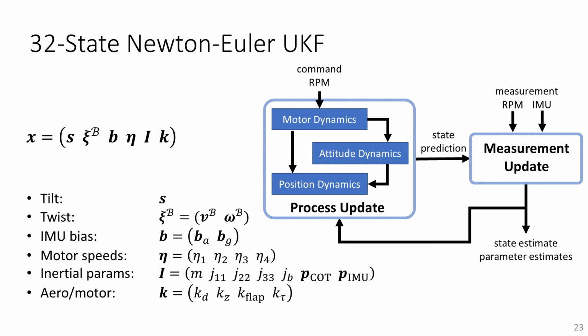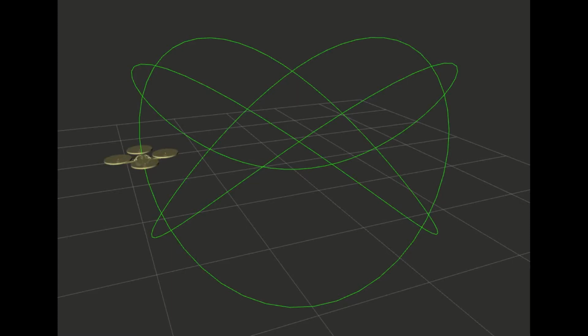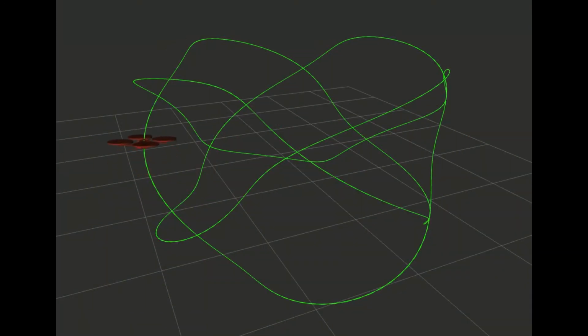Intuitively, this makes sense. Some angular excitation is necessary to estimate the rotational inertia. In our experiments, we adopt Lissajous patterns using sums of sines. Long period changes excite large changes in velocity without saturating actuators. At the same time, short period components excite high angular accelerations, making it easier to estimate principal moments of inertia.